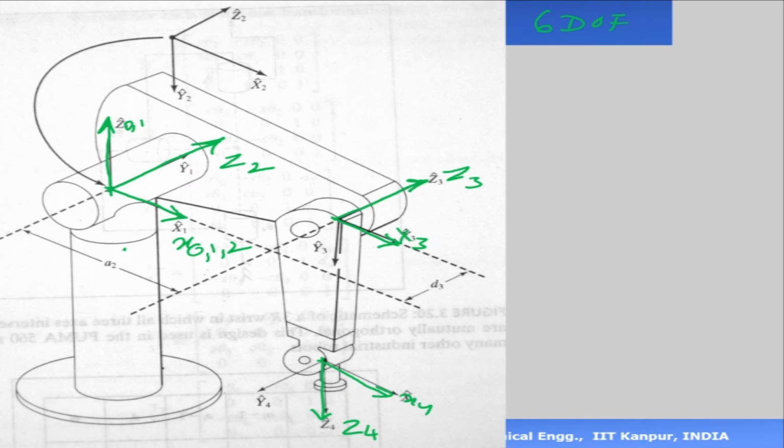Now look at the distances between the various origins of the frames. Please note this very carefully. This is the origin of frame 0, 1 and 2. I could have taken the origin of frame 2 here also, but just for simplicity, I'm making it here. So that's my z2 axis. Now the origins of 0, 1 and 2 are the same point. Origin of 3 is here, so that's frame 3. 4, 5 and 6 are there. Now, y-axes are not required, so we need not draw them.